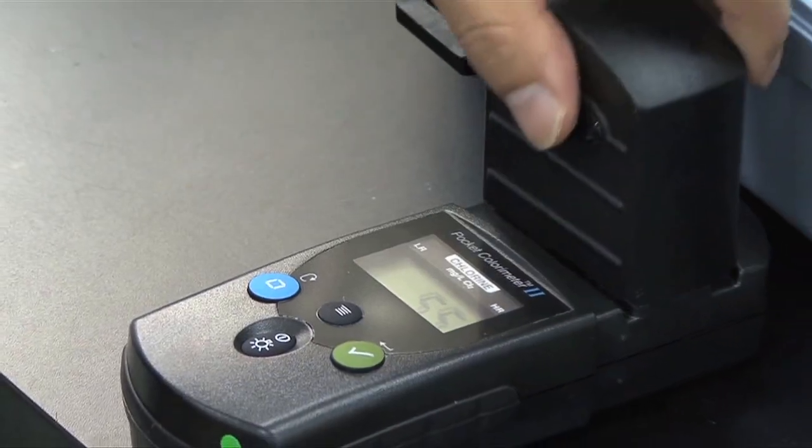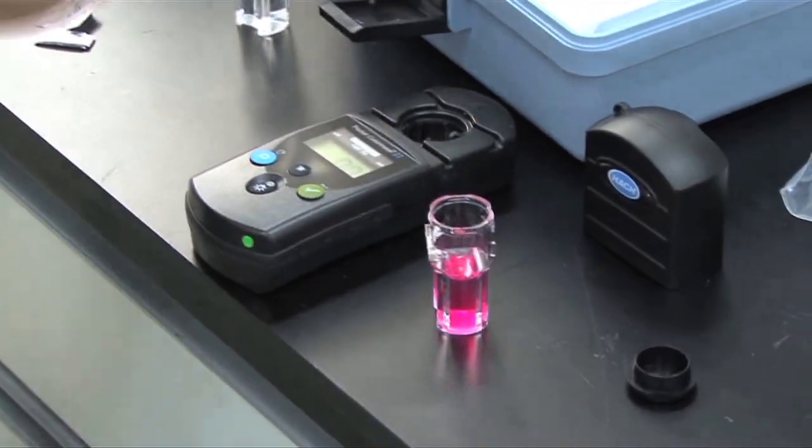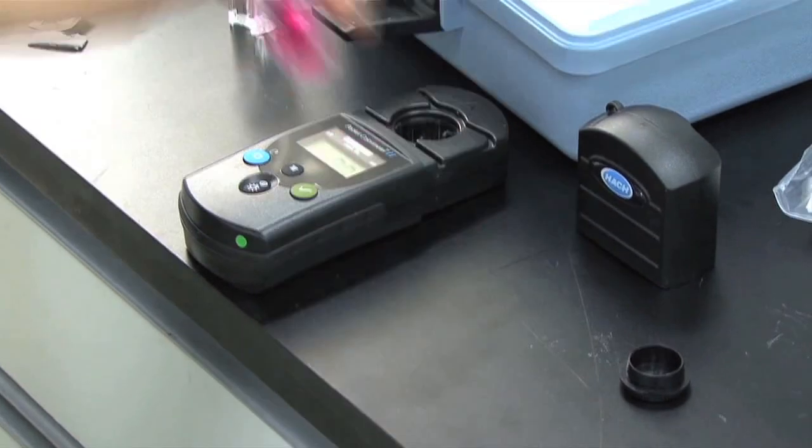Step 3. Buffer solution on the right side of TRO sensor. 1. Pour distilled water to the line. 2. Close the cap and mix thoroughly. 3. Do not add DPD powder.